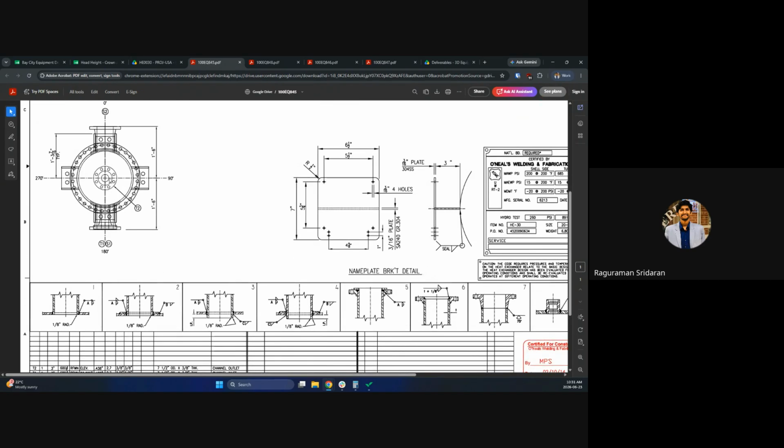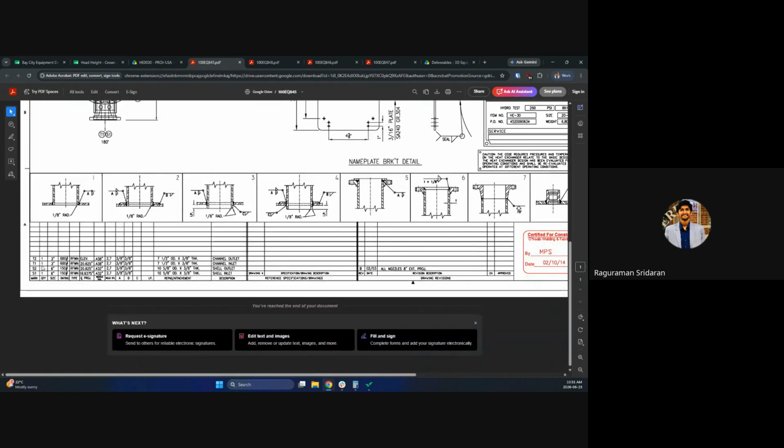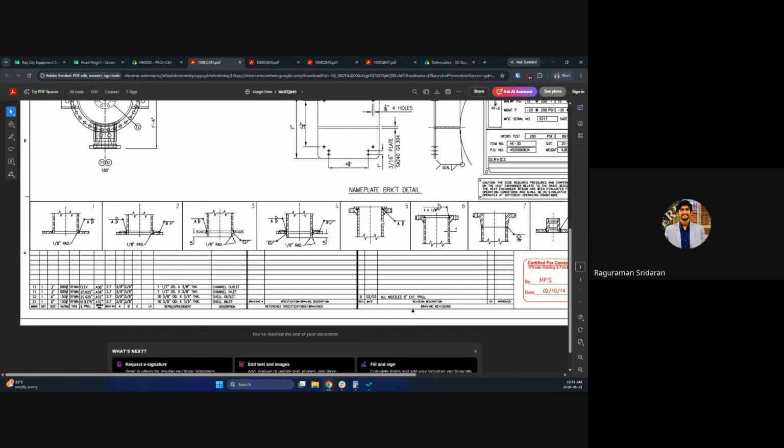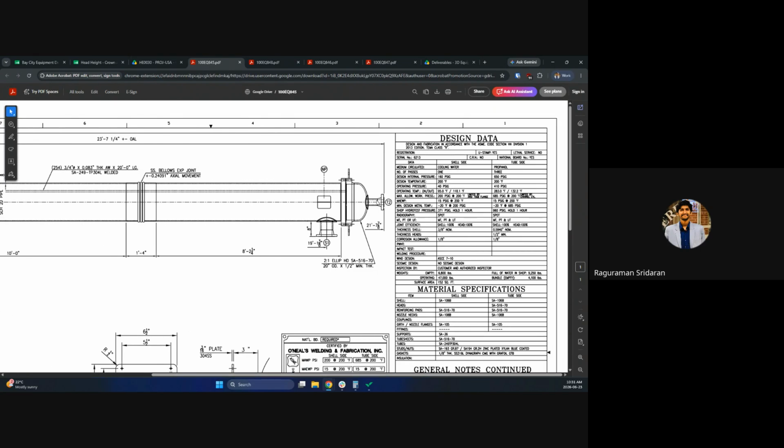And we see here we have the information about the nozzles. So this is the plan view of the drawing. Towards the bottom we have the bill of materials where we can find the number of nozzles that need to be created. So there are 4 nozzles that need to be created. So let's see, we start with the one here towards the right, the T2.